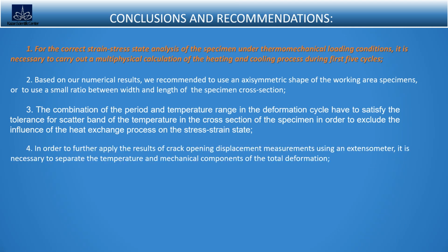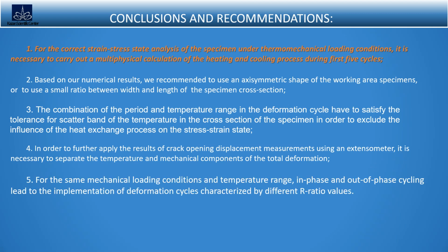In order to further apply the results of crack opening displacement measurements using an extensometer, it is necessary to separate the temperature and mechanical components of the total deformation. For the same mechanical loading conditions and temperature range, in-phase and out-of-phase cycling lead to the implementation of deformation cycles characterized by different R ratio values.